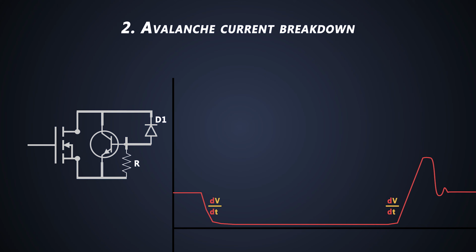The diode's recovery current and recovery dI/dt might cause the current to flow through the diode. And due to that, voltage will be generated across the base and emitter of the intrinsic transistor. If this voltage generated across the resistor is high enough, then there will be a false turn-on of the parasitic NPN transistor in the MOSFET, causing permanent damage.